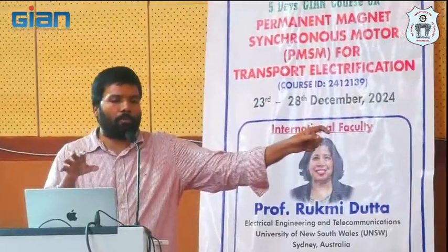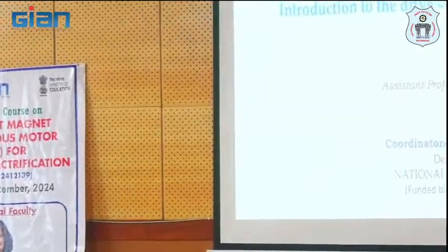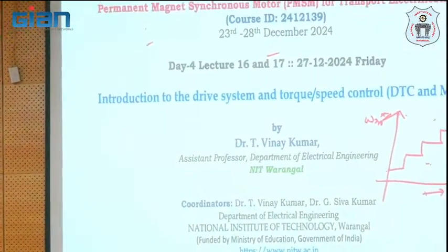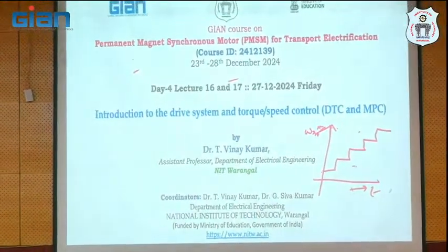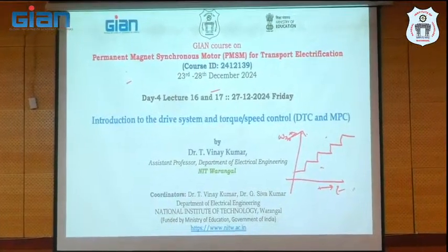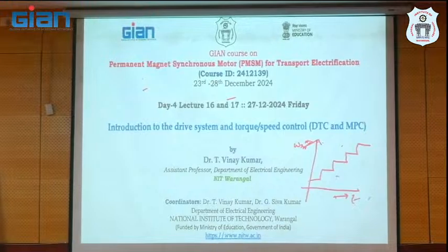Later, once the rotor poles are locked, as a scholar you need to understand the inertia of the drive. Once you know the inertia of the drive, based on it we can decide the time period for each stage. If inertia is more, you have to take a long period. If inertia is very low, you can reduce the time period.